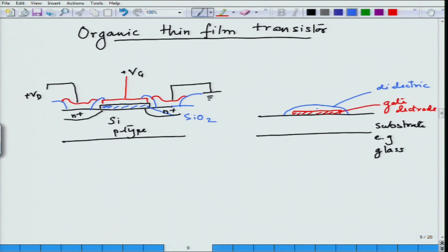I have a dielectric film on it, and now I want to deposit the silicon on top of it, or the semiconductor that I am going to study. So, I need to make the contacts for the source and drain again. I will make source and drain here. This is my drain, and this would be my source, and then finally I make the deposition of the semiconductor.